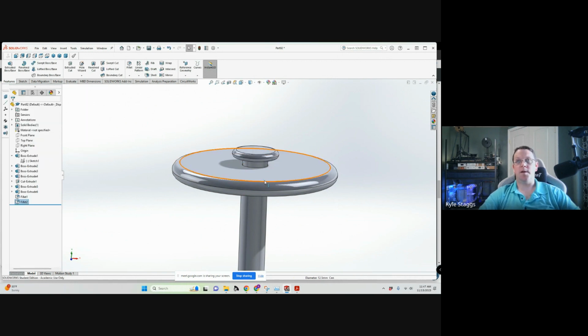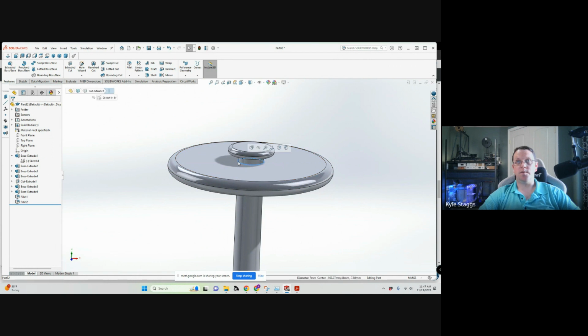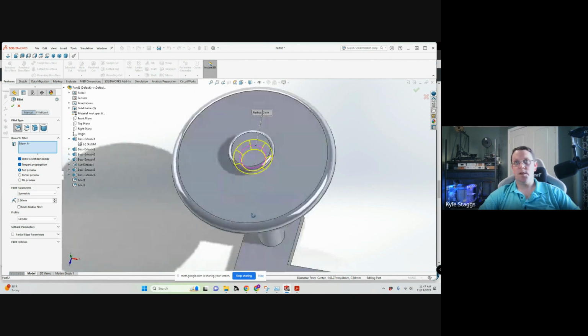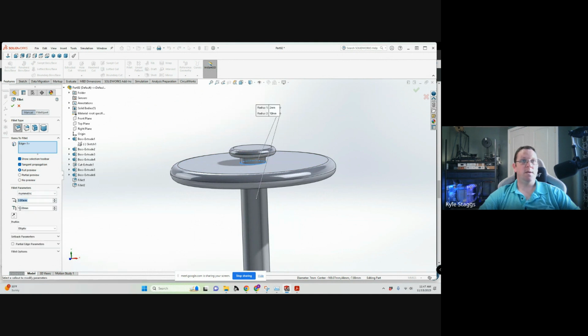And then you have a fairly clean cap. You can also do a fillet on that surface as well. And that one you can do something more like 2 millimeter. And that will help to reduce. You can do it asymmetric even.